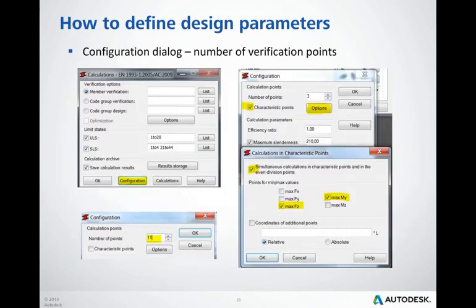The verification of a section capacity is done in the declared number of divisions along each calculation element generated along a bar. As I already mentioned, the calculation point defined along such a bar splits it into two calculation elements, meaning that the check will be done on both the left and the right side of the calculation node. This is why I suggested defining a point load with the generation of a calculation node, so that this point is not skipped during the code checking of a bar.